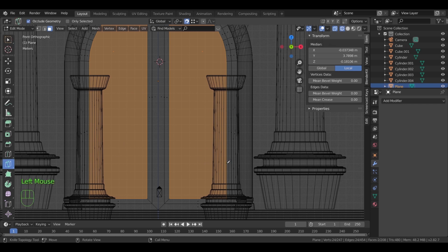How does the knife tool work, you ask? It's simple. Press on any point you want to start with, go to the next point and select it. To finish the process, hit spacebar. Also, press C to restrict movements to horizontal or vertical lines only.